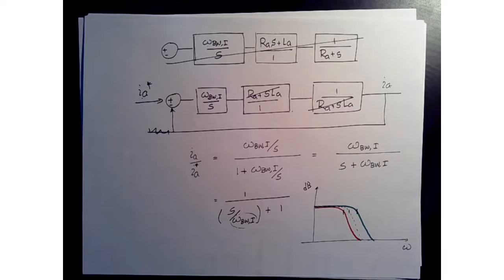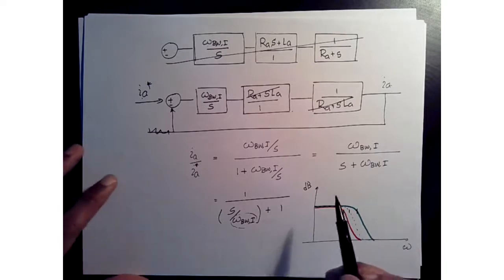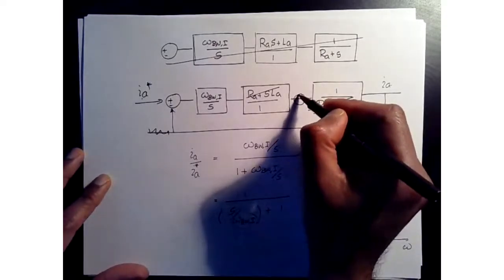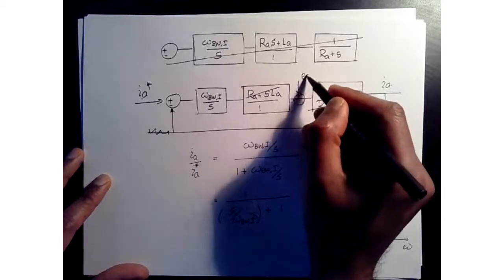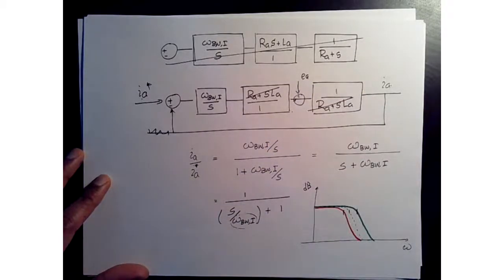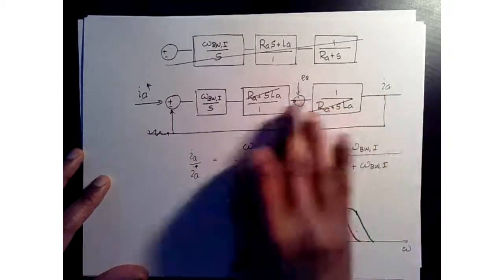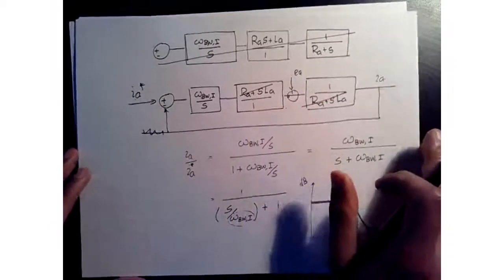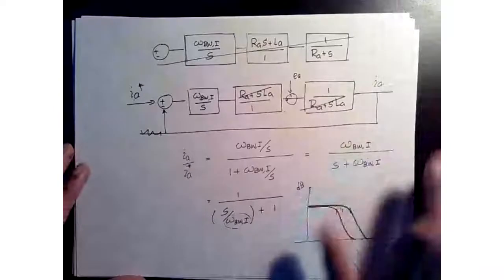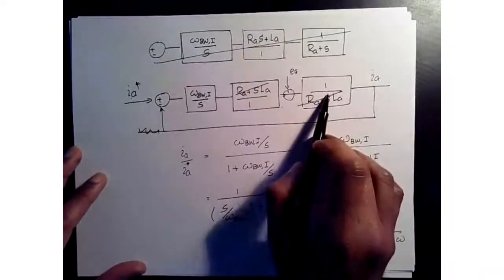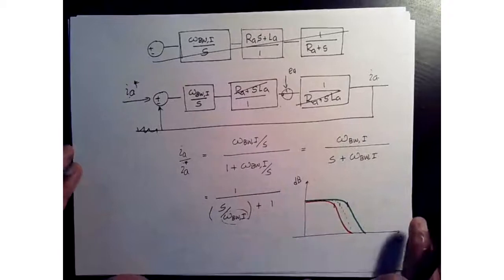Yeah, so I recommend you guys try this in your Simulink. You can build a motor model, build a simple controller, see how it looks, and now you can even test it with different speed variations. Your controller will still perform because your back EMF is still there in your motor model. The current loop dynamics will treat the back EMF as a disturbance, and it'll try to adapt based on the variations you have, and it'll still perform like we expected it to perform.